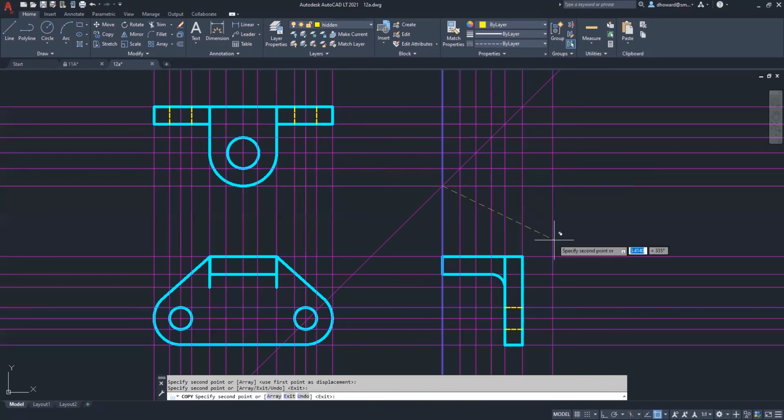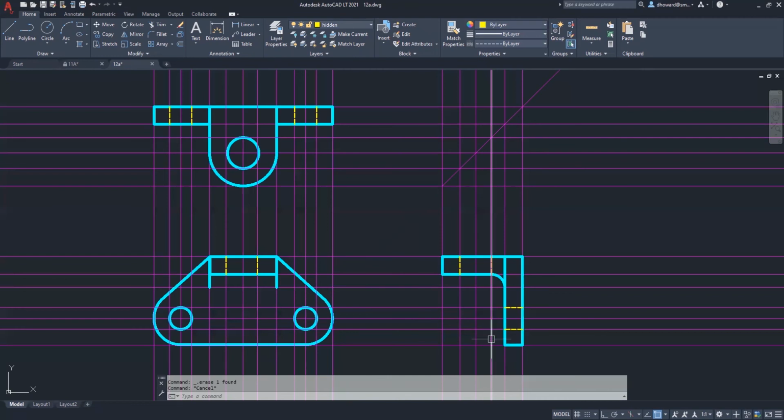All right, I've got those construction lines created, and now I can draw its hidden lines. Good. Okay, now for the center lines. And the center lines, remember, we need to be able to draw them 1/4 of an inch beyond the object. So I need to offset my lines and arcs 1/4 of an inch.